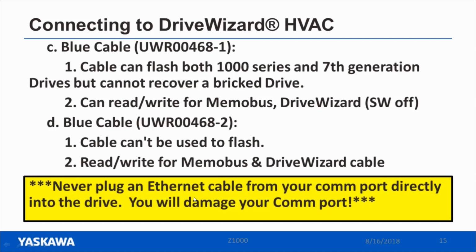Worth mentioning, never plug the Ethernet cable from your COM port directly into the drive. I know, it might look like, hey, I can plug it directly in and it's no problem. You're going to damage the COM port on your computer if you do that. So never plug that in. You need to interface it with the serial cable or one of the other connection types that we ran through.